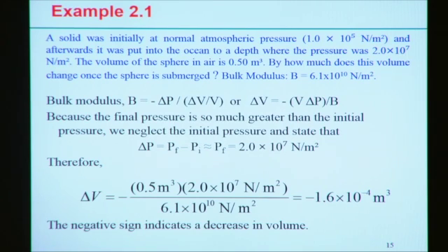It is noteworthy that the units of all the moduli are equal to the units of stress. Now the bulk modulus, if we directly apply it, is the change of pressure over delta V by V. Here the sign convention is considered negative depending upon the application of the pressure, and whether it is expanding or squeezing. So the change of volume can be represented as the original volume into the change of pressure divided by the bulk modulus.